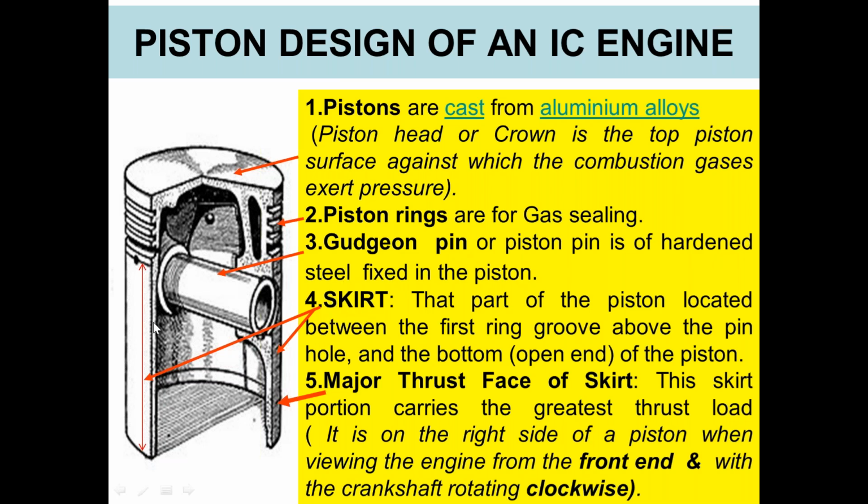The skirt is an important part. You see the skirt here. That part of the piston located between the first ring groove above the pinhole and the bottom open end is called the skirt. Major thrust face of the skirt: this skirt portion carries the greatest thrust load.